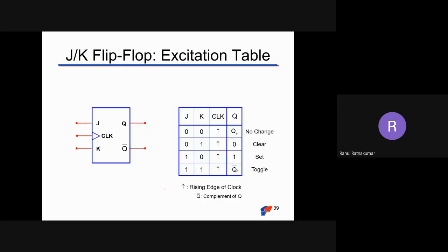Now this is a JK flip flop. Here also you can see it is activated on the negative to positive edge of the clock, the rising edge of the clock. So 0 0, there is no change. And 0 1, K is 1, so Q is 0, Q bar equal to 1. And J equal to 1, it is set, Q equal to 1. 1 1, it is toggling. So we are overcoming the prohibited or forbidden condition and it just toggles in that condition.